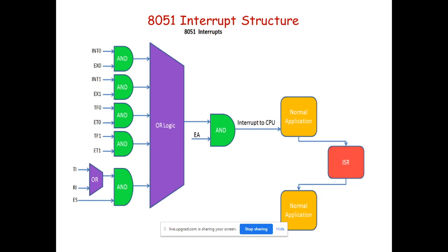In serial communication, we know that there is only one pin. In parallel communication, all 8 bits are moving from one device to the other. But in serial communication, all bits are not moving at a time. There is only one bit to transfer, and only one wire between the two devices. One by one the bits are moving. When all 8 bits are out, at that time TI becomes 1. Similarly, when all 8 bits have entered the controller, RI becomes 1, meaning a receive interrupt is generated.